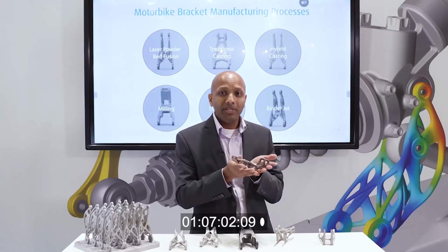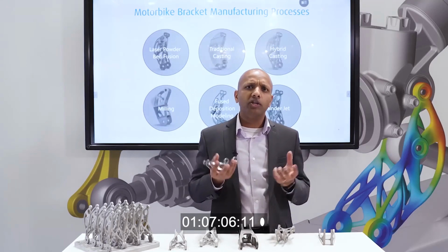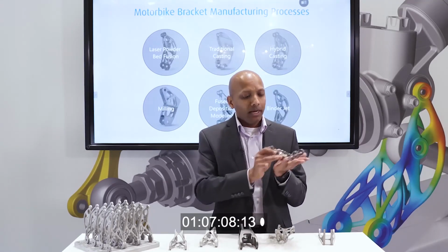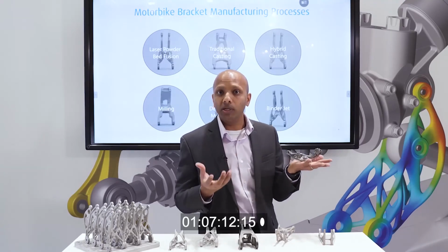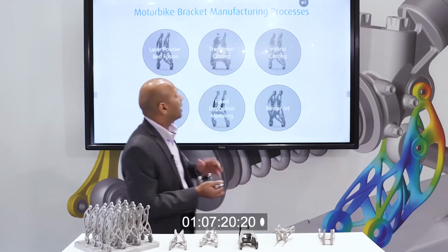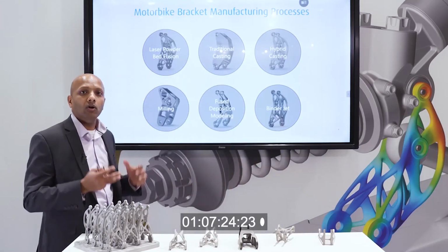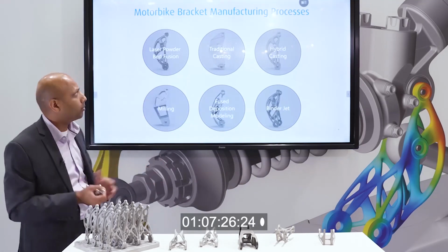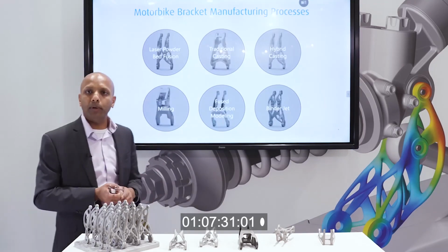But when they put this green part into the oven, the part shrinks. And typically the part shrinks toward the center of gravity. In Inspire, we can assign the center of gravity as a manufacturing constraint, so the design looks much different than what we saw for something else. Again, it goes back to the philosophy of Inspire, as you can see on the top: choosing the best manufacturing method, by an engineer, by a designer, to come up with a particular design.